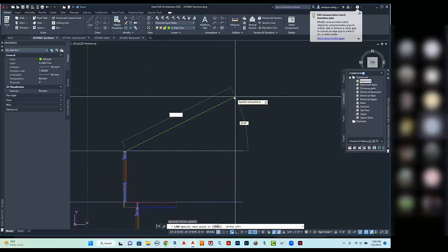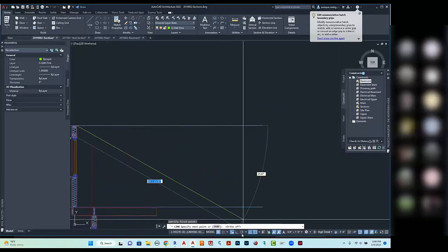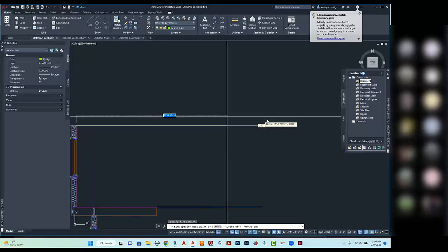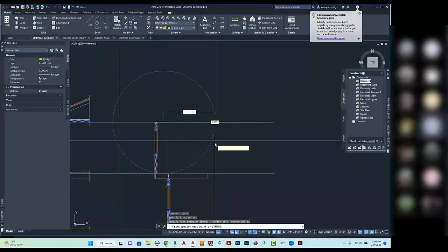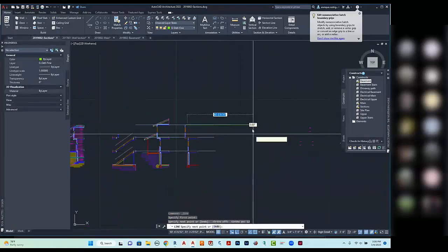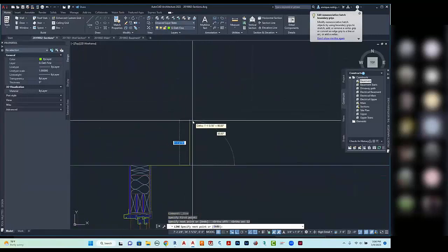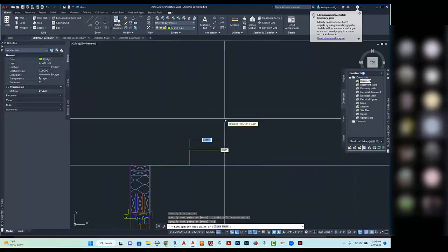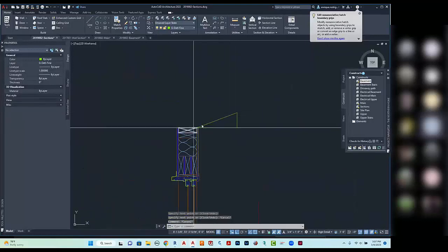Okay, so the horizontal, I'm going to go ahead and put my ortho back on. I'm going to draw 12 units this way. That can be 12 feet or 12 inches or whatever. I'm going to go 12 feet. And then I'm going to go, actually I went 12 inches there. And I'm going to go 4.5 inches vertically. And then what I can do is draw the diagonal, and that represents the bottom of the rafter.